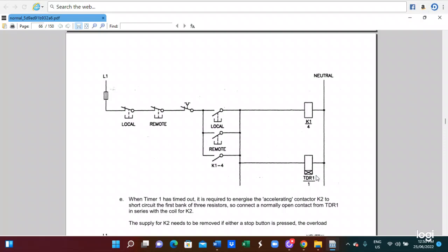And this is the time delay. In this case, you connect the control. This is called the holding coil. And here is the switch. This is the time delay function. So you can control the drive or you can do this time delay function. The time delay function control can be utilized this way. This means that when you connect, firstly the time delay contact will be energized. After some time, the main coil is energized. Then the motor will be controlled. So by connecting this circuit, firstly you have to energize the time delay function.